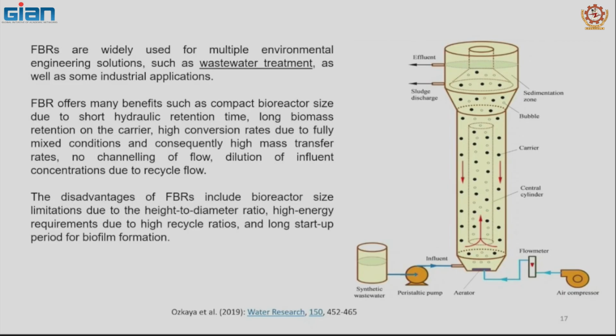Traditional treatment techniques for organic pollutants are oxidation ponds and activated sludge systems, where huge space is required. But if your industry is located in such a place where land availability is low and land cost is too high, a compact treatment system is necessary, where this fluidized bed system can be used.